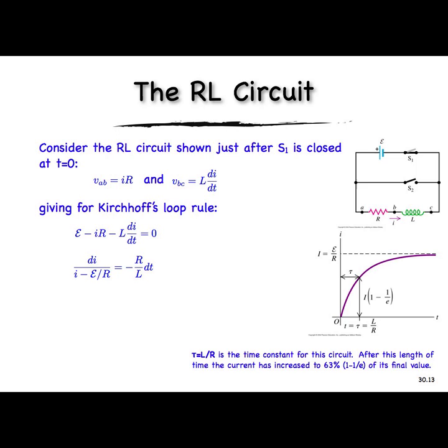So now we'll rearrange the circuit. And what I want to do is solve for the time rate of change of the current through this inductor, or in the circuit. Okay, so I'm going to be interested in solving for I. And we can see that it depends on time, so there's going to be a time dependence to it. So this is a differential equation. It's one that's particularly easy to solve, though. It's a first-order differential equation.